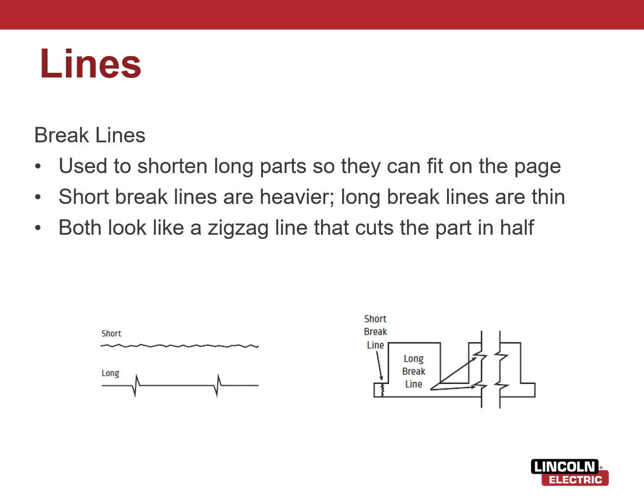Break lines are used to shorten a part so it can fit on one page. Just imagine the actual dimension of this is tens or maybe hundreds of feet long, but you have a lot of smaller, medium sized, and large stuff all over the drawing. To keep everything proportionate, this would take up a ton of space on that drawing. So instead of having the full length in there, you do a break line. That's what these jagged lines are right here.